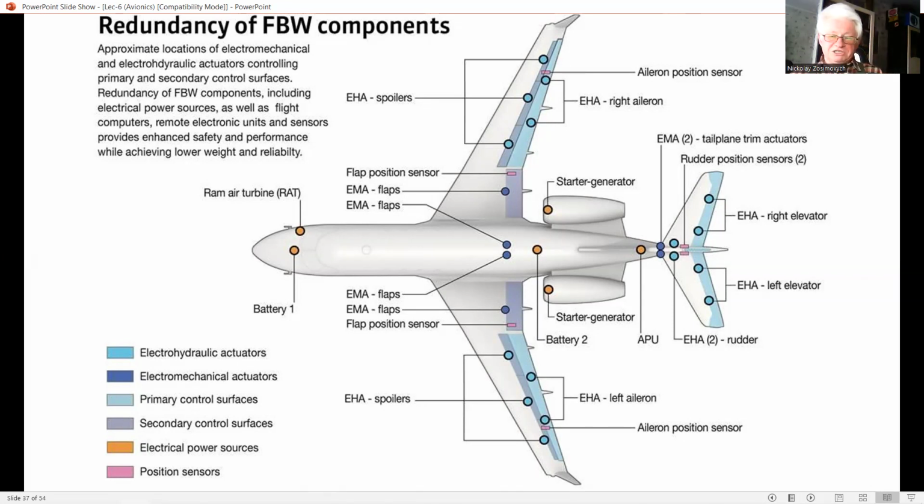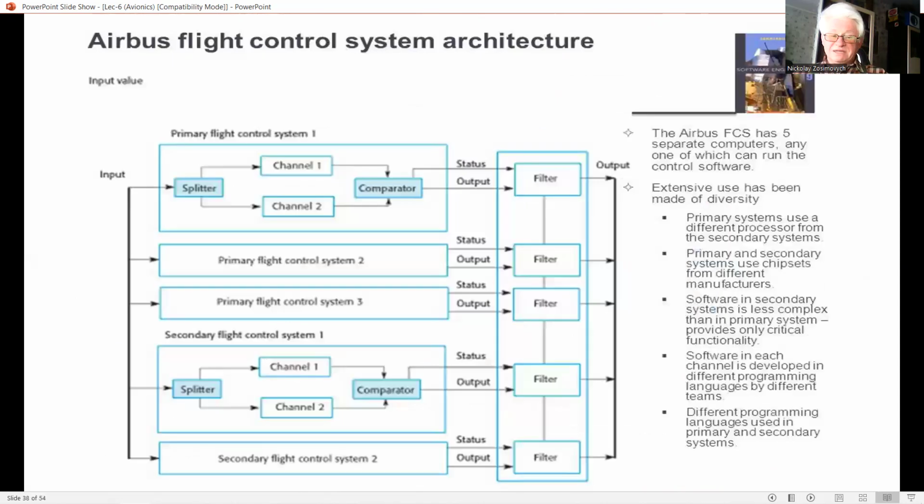The incorporation of a monitoring system to check the correct functioning of a channel to a very high confidence level can also enable a failed channel to be identified and disconnected, and this leads to an alternative failure survival configuration known as monitor triplet.